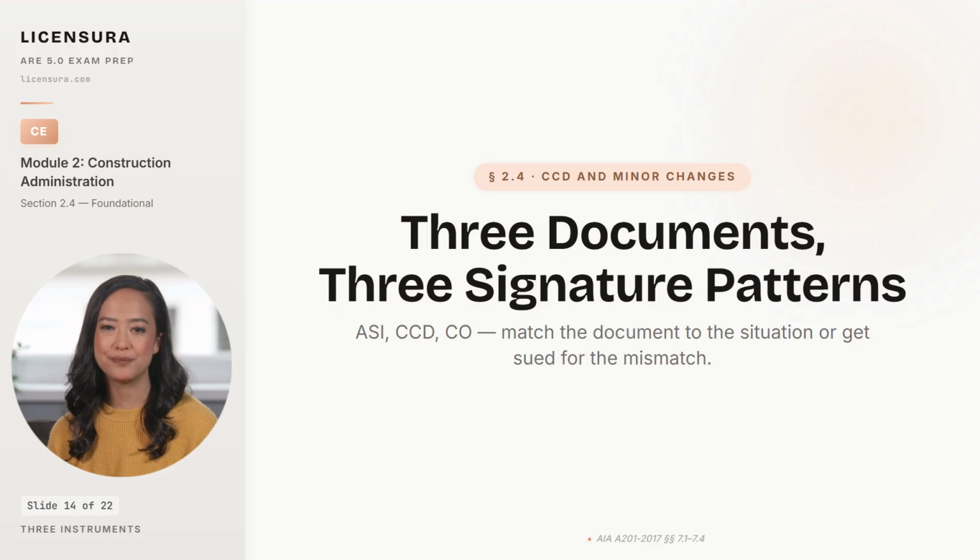AIA G701. And the Construction Change Directive, the CCD, AIA G714, is the document the exam loves because it is the unusual one. The owner needs the work done now, the contractor has not yet agreed on the price, and the owner directs the contractor to proceed anyway. The CCD is signed by owner and architect only, not by the contractor, and the contractor is contractually obligated to comply while the cost gets resolved afterward. 3 documents, 3 signature patterns, 3 situations. Confuse them and the firm gets sued for unauthorized direction.